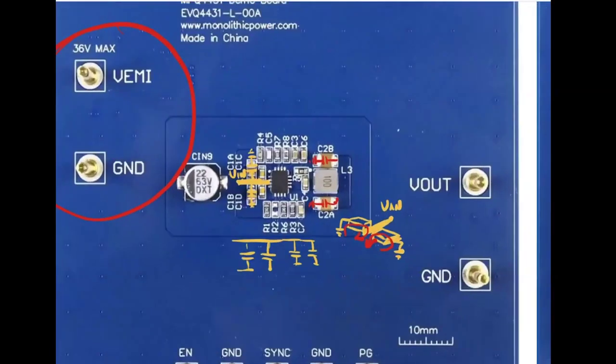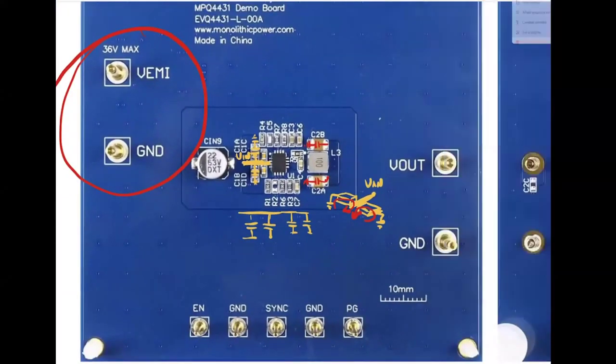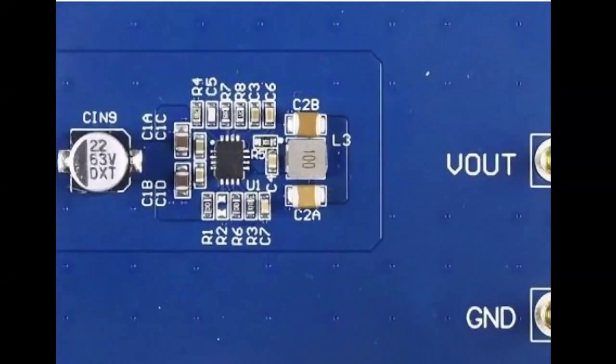Okay. The idea is that for the input capacitors, the ground terminal is here. This is the ground terminal, and this is Vin. But for the output capacitors, this is the inductance, and the 2 capacitors are located here. One of the things that you get with this situation is that the current that is trying to go out from your system and is able to pass through the inductor is returned in different phases through the capacitors. So this is the correct orientation.